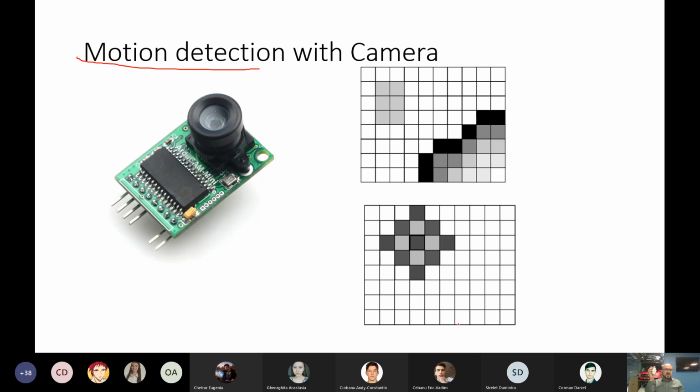Everyone has a mouse, and how does it work? Very easy. It's measuring the movement of defects on the table. Let's see how we can do that. It makes a picture, and after making the second picture, it moves it and checks the picture moved in this direction, this direction, this direction, and looks for which of the moved defect images is the best match with the current picture.